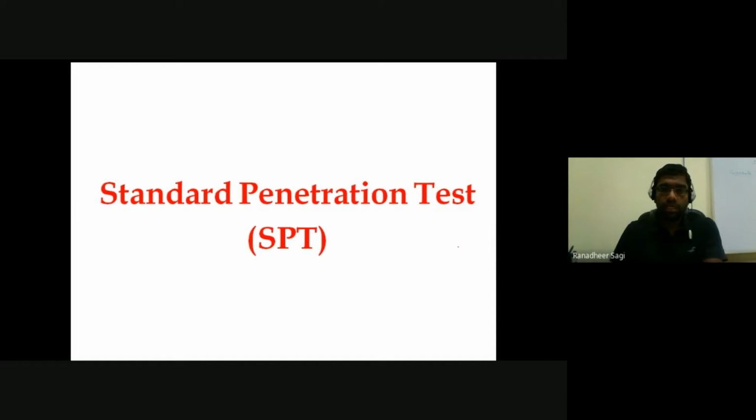In this standard penetration test, we are going to penetrate a sampling tube into the ground. We push the sampling tube into the ground by applying a standard load from the top, an impact load, where a standard weight falls freely from a standard height and hits the top.